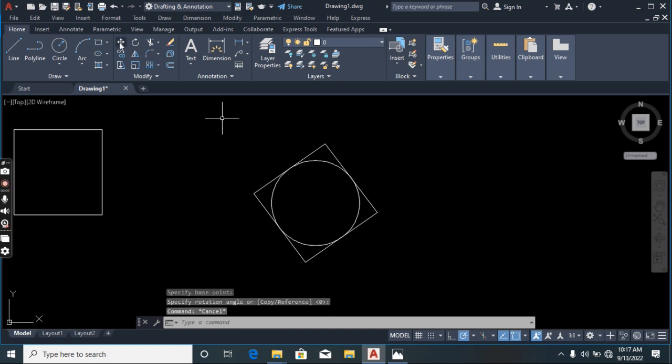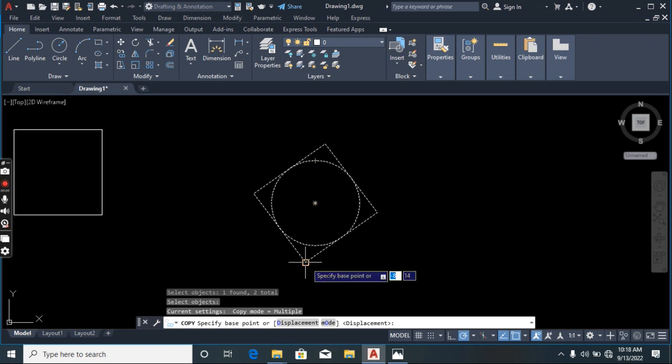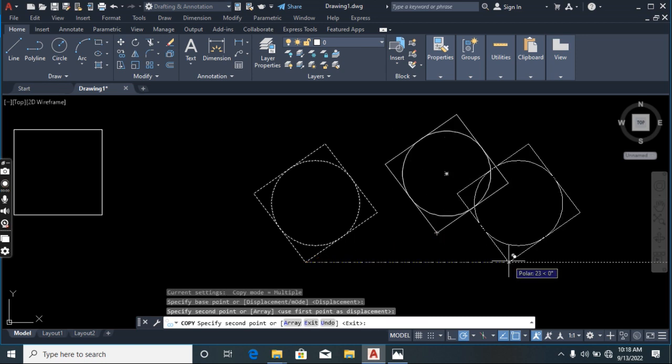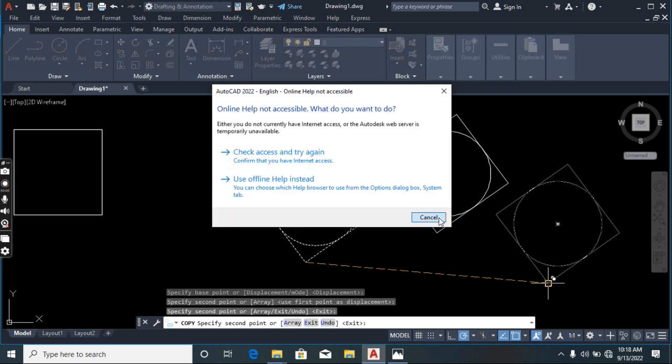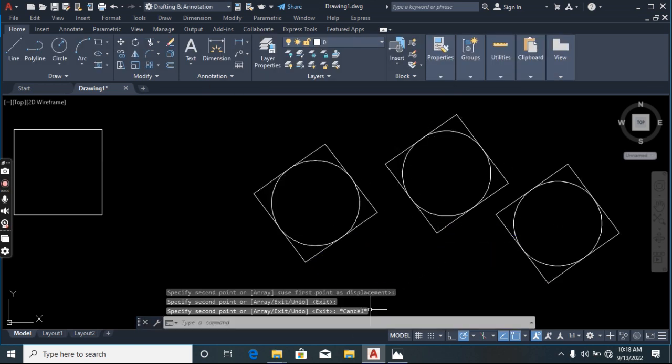And also, what again? These are copies you must have drawn and you want to copy. You can click on your drawing, or you can just go on the copy and click on this, and the same thing, enter. What is it saying? Specify base point. Okay, now you want to copy, you need a base point too. You just want a base point like this, so you can copy as many as you want. So you escape when you're done.